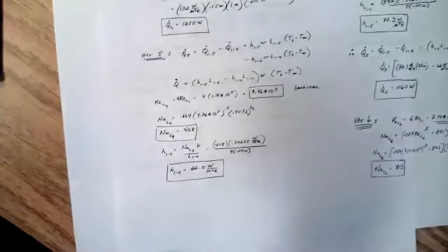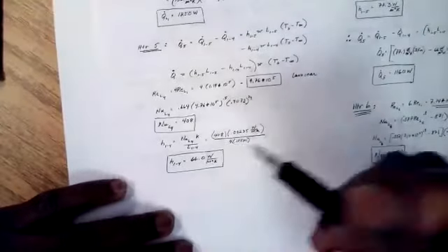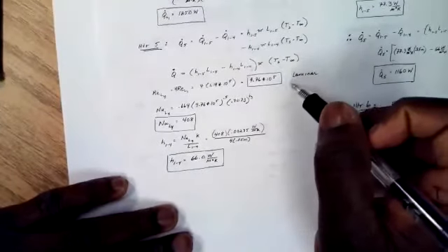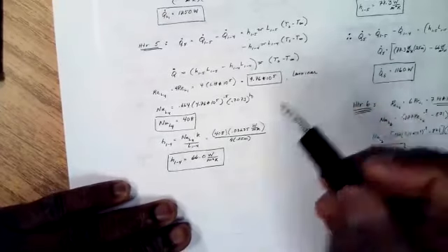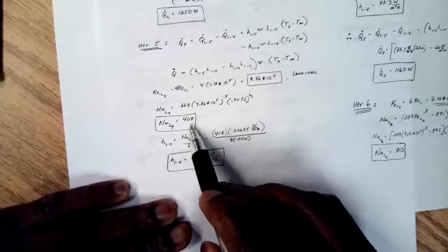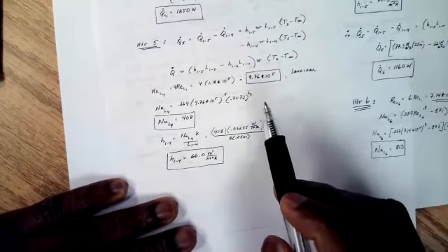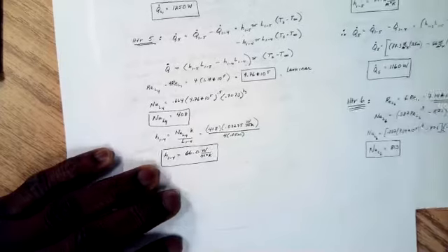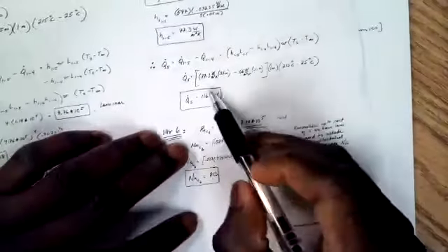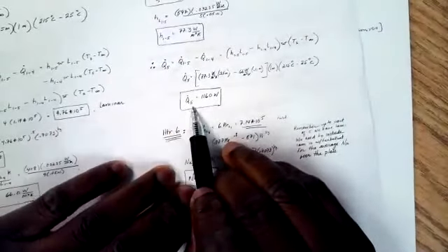It confirms the calculation that we did earlier to show that it's laminar all the way to the 5th heater. Then we can evaluate the Nusselt number, and find our h, and once you get h, you can then calculate and find Q5.